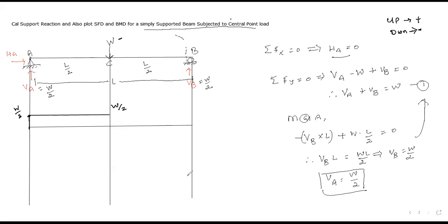We have only 3 minutes. Please, fast. No, we have not considered it. Where have we done it? Have we added or subtracted the W load in the diagram calculation? We have not. Right? Now we will either add it or subtract it. Now what is the nature of W? Upward or downward? Downward. For plotting a shear force diagram, downward load will be a -1.